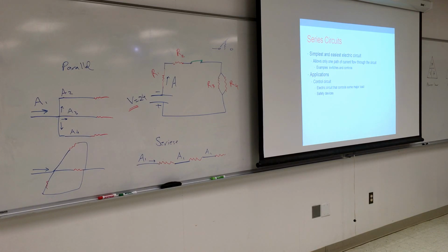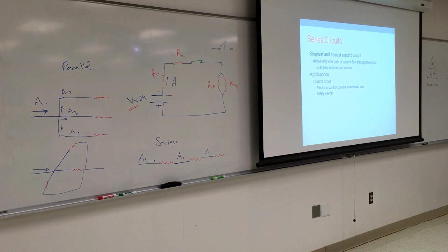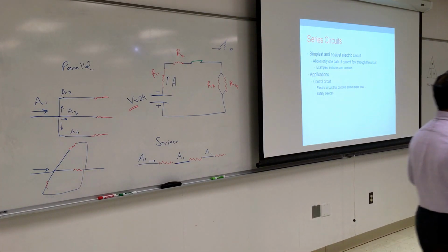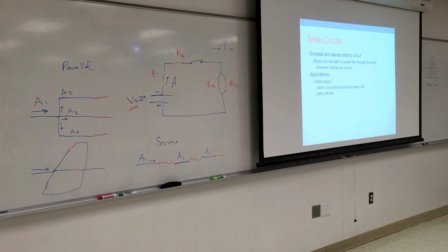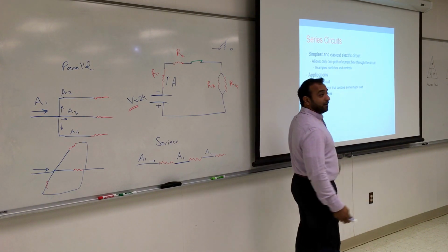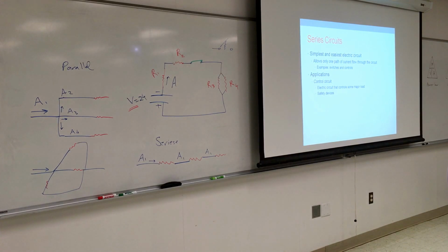They had a fuse. That's for load. If this one was cut or shorted, the circuit will not be energized. The 2 other ones are control. So there are 2 main purposes for a series circuit. What are they? Control and safety. Those are the 2 reasons we use a series circuit. Because if one of those controls is out, the whole circuit is out. Otherwise, what is the point? I'm not controlling that circuit.